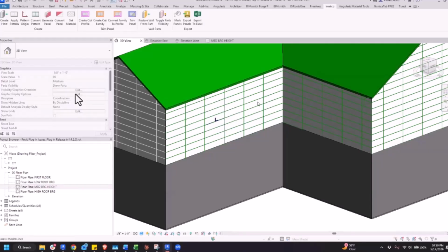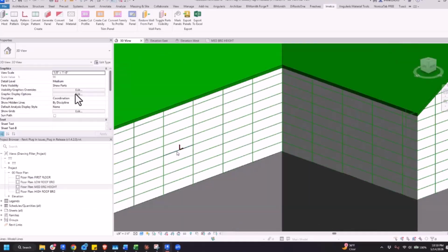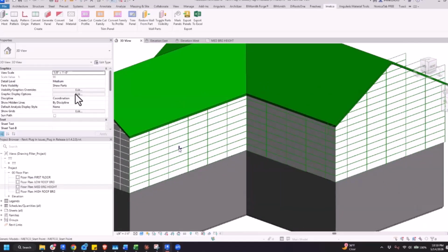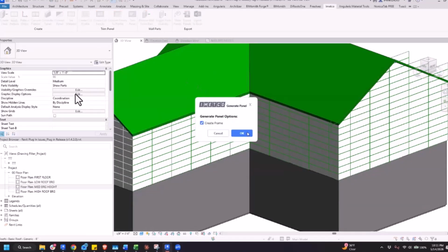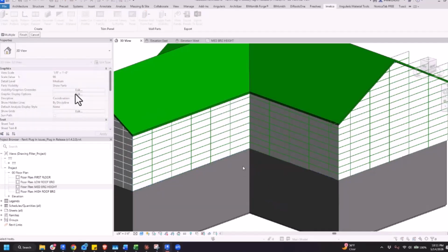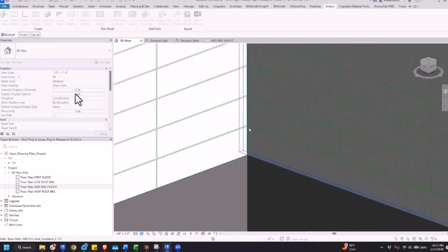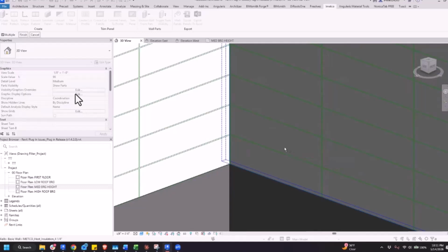One thing that can cause issues is if your line is right here, like actually on the corner. Literally right there, that would probably cause an issue. Fair enough. So let me undo that. Since there is no line here, and this is going straight across, the computer will see it as a mitered system. So now that we have origin points on all 3 walls, what we can do is grab the convert pattern tool, select these, convert the pattern.